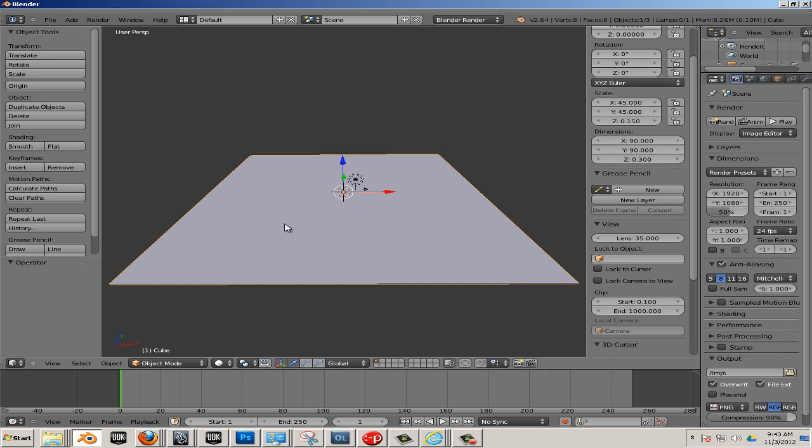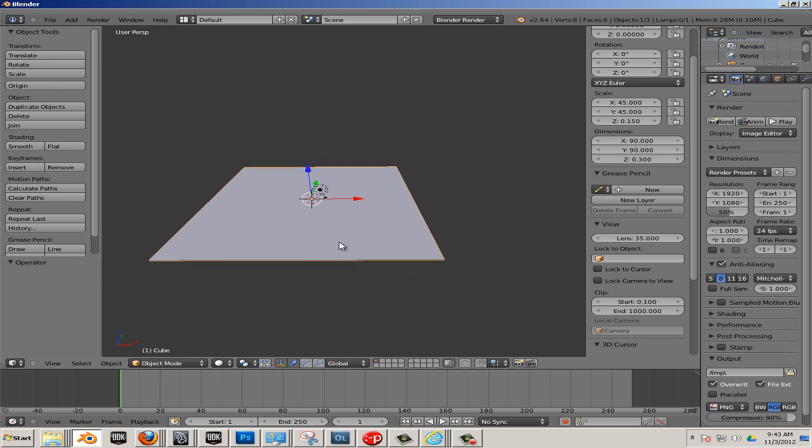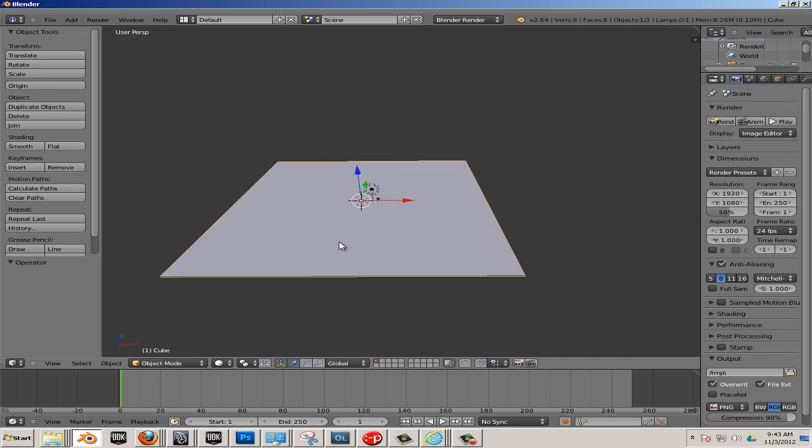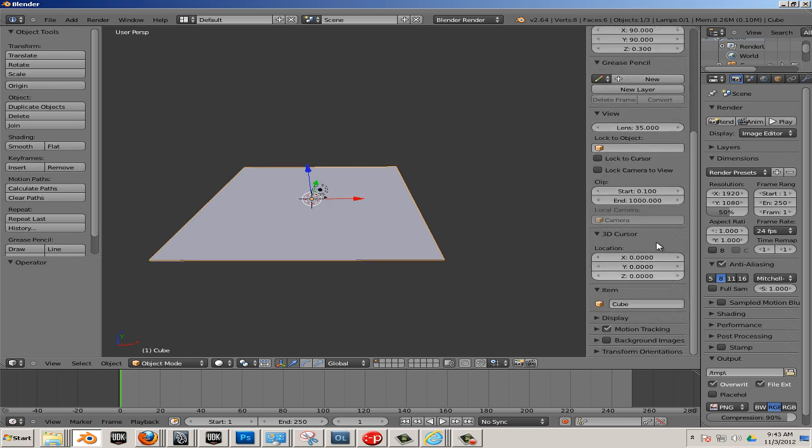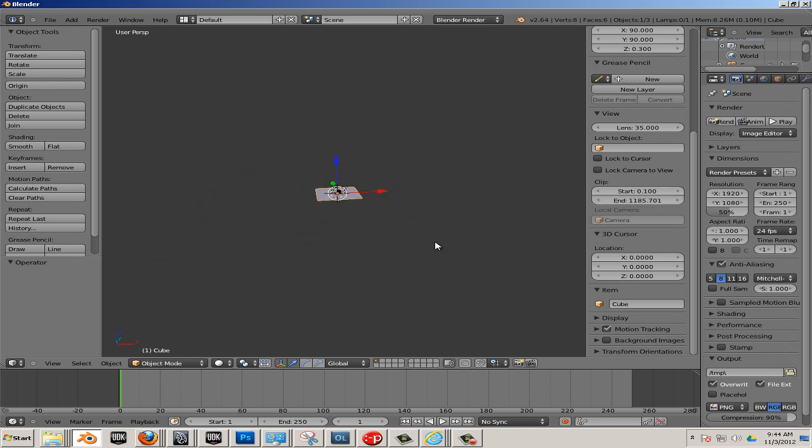Okay. So as you're going through here, let's say it was 120 millimeters. Well, that looks really huge in Blender. Here's what happens if you hit N and you look down. There's a clip end. If it gets too big as a part is concerned, you can make the clip end go further, and that way you can see more of it without it clipping out. So I can zoom way out now. See how it's clipping into the background? Well, if I expand this, I get more buildable area.